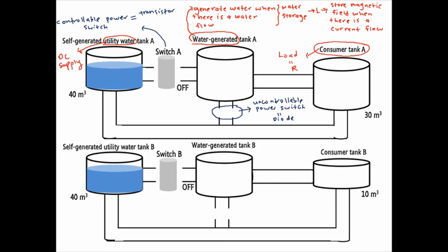In the DC converter circuit, a diode is used to maintain the connection between the inductor and the resistive load. As a conclusion, other than the capacitor, each DC converter circuit must consist of the input DC supply, a resistive load, an inductor, one controllable power switch, and one diode.